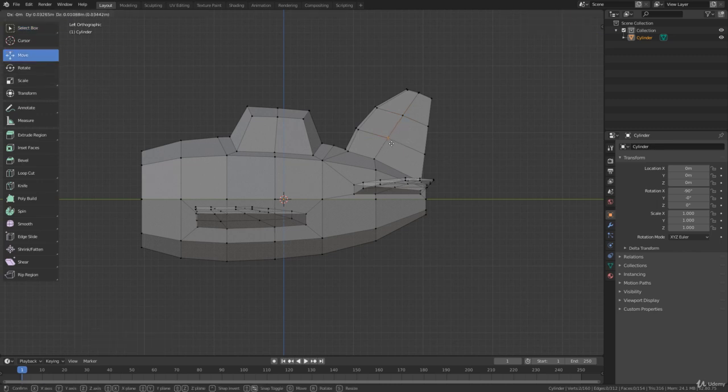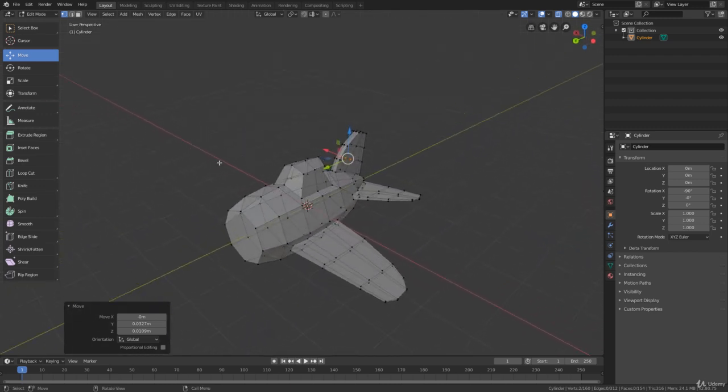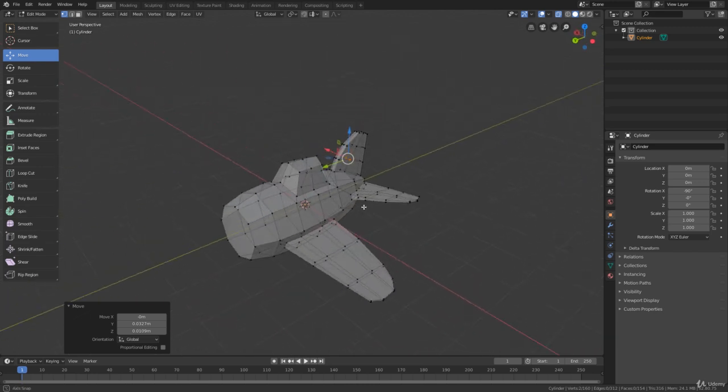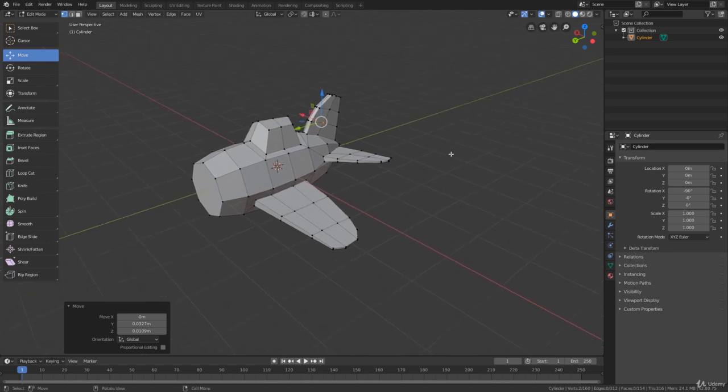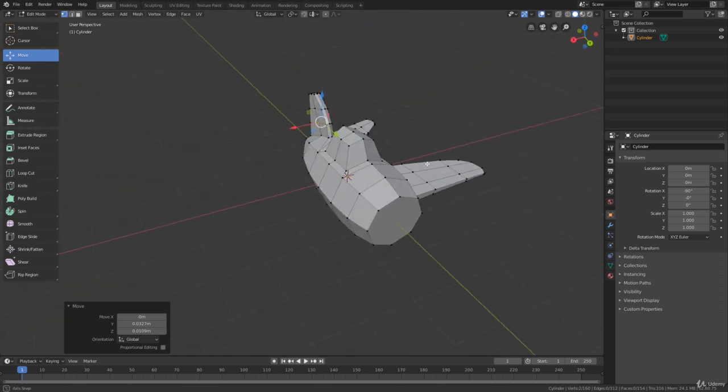and make them straight. And what we are seeing here now is a perfect example of the kind of adjustment that we have to do when we are doing polygonal modeling. Okay? This process needs a lot of adjustments. So we need to select vertices, move, adjust. Select vertices, move, adjust all the time. Okay? And now I can disable the X-ray mode because we finished the modeling of this side of the airplane.